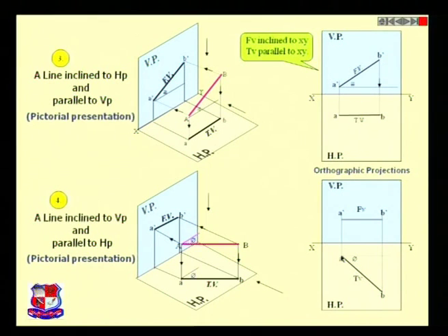As you can see over here, the angle with the vertical plane is called phi. This angle is something given. Let's say this angle is given as 60 degrees. This length would be a true length, because if we take the projections of it from the top view, then we can have exactly parallel projection to it, and we can get the true length of this line. So these are the basic concepts of any projections of a line.